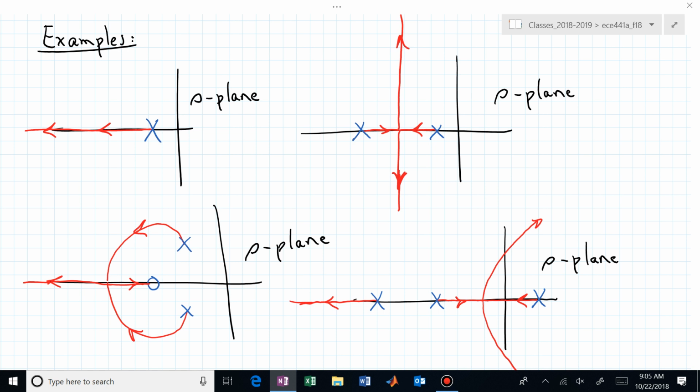Why do we know that the upper left root locus simply moves from the pole all the way to minus infinity and never gets off the real line? Why do we know in the upper right that the root locus actually leaves the two poles, but they leave and approach each other, and then once they merge, they immediately break off the real line?